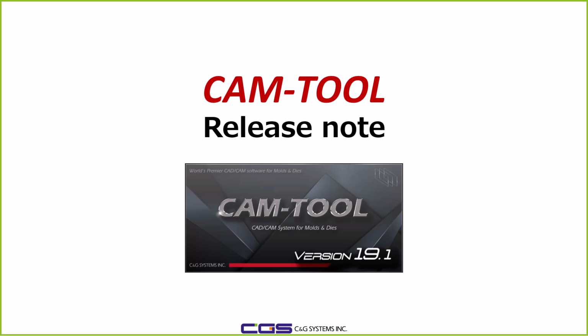All right, so a few improvements coming in today. First is when you copy a calculation process list, you now don't have to set your product shape or your work or your material. They're all copied over with it, so you don't have to reset that. Also, material has been added into the tree, making you able to set the material, and therefore when you load the tooling database on any profile, it will only show any cutting conditions you have set for that material, so it's just another form of filtering.